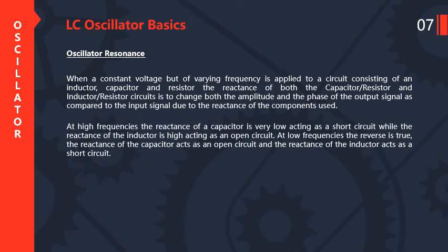At high frequencies, the reactance of a capacitor is very low, acting as a short circuit, while the reactance of the inductor is high, acting as an open circuit. At low frequencies, the reverse is true. The reactance of the capacitor acts as an open circuit and the reactance of the inductor acts as a short circuit.